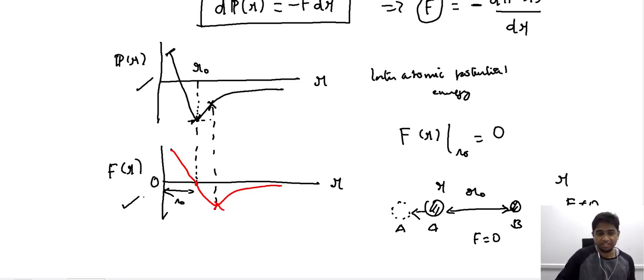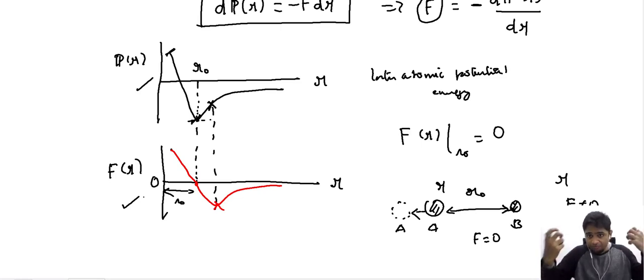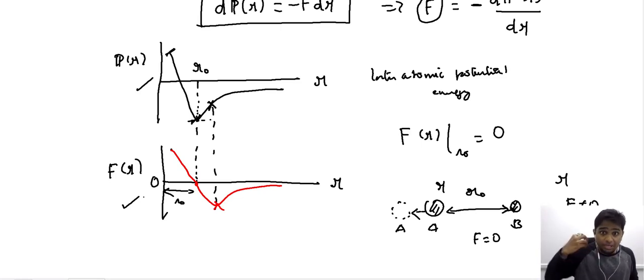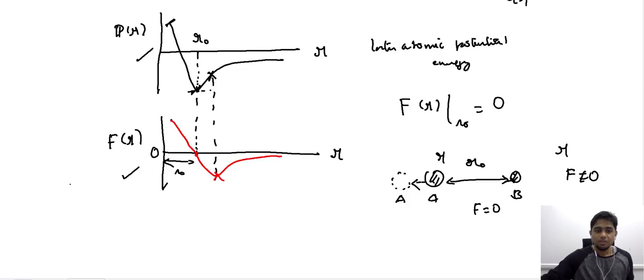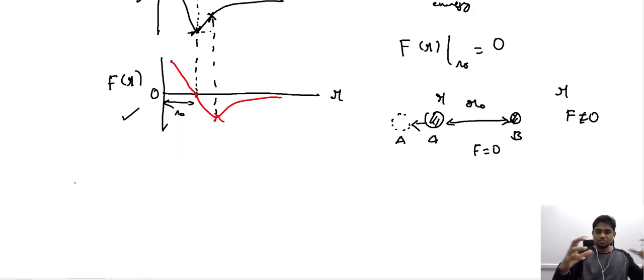Now what this plot helps us understand is how the force that we impose translates the positions of the atoms. There is a load that we impose, it translates the positions of the atoms, and when the position of the atom varies from R0, an interatomic force is introduced. And now when you remove the load, this interatomic force is responsible for the atoms getting back to their original position.